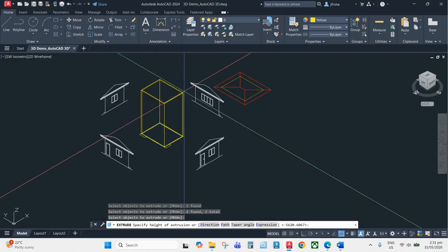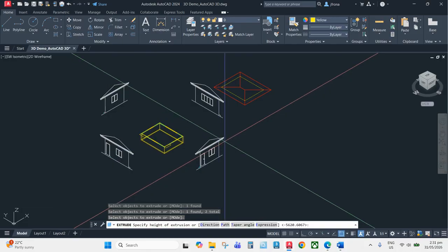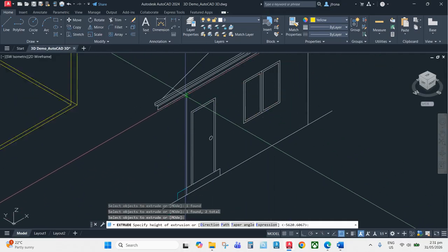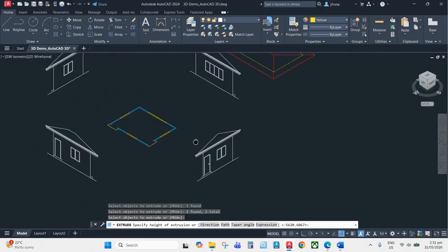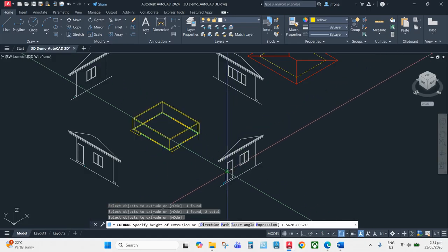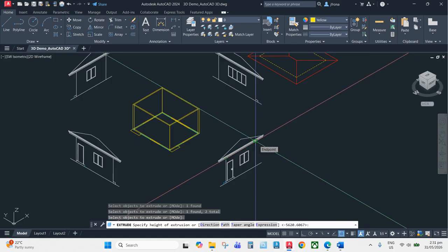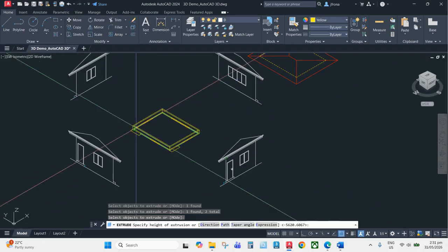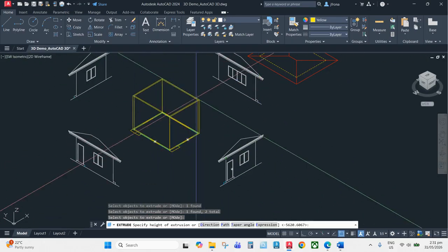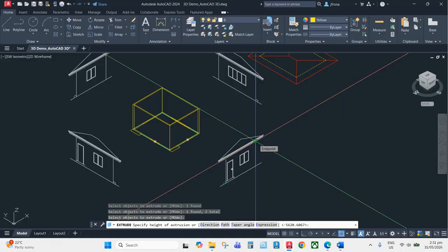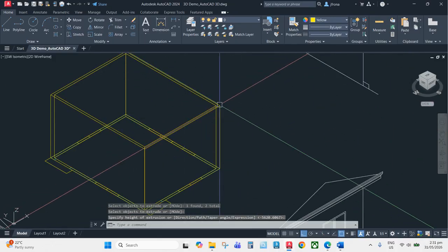Now, since we are using our elevations as our basis, we're going to use them as the basis for the height of our wall. So if we just zoom a little back, when you select the height of the wall, you can see what you're seeing here on the wall is already reflecting the height of this wall. So click that, and then we have this height.